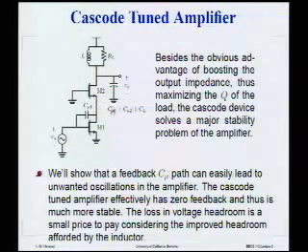Also, you might note that a cascode does reduce the headroom a little bit, right? Because now this transistor, this node can't swing all the way down to VD-SAT. It has to keep, essentially has to keep this transistor alive. But because we gained all this headroom by using an inductor, it's really not too bad of an issue. It's not too much.